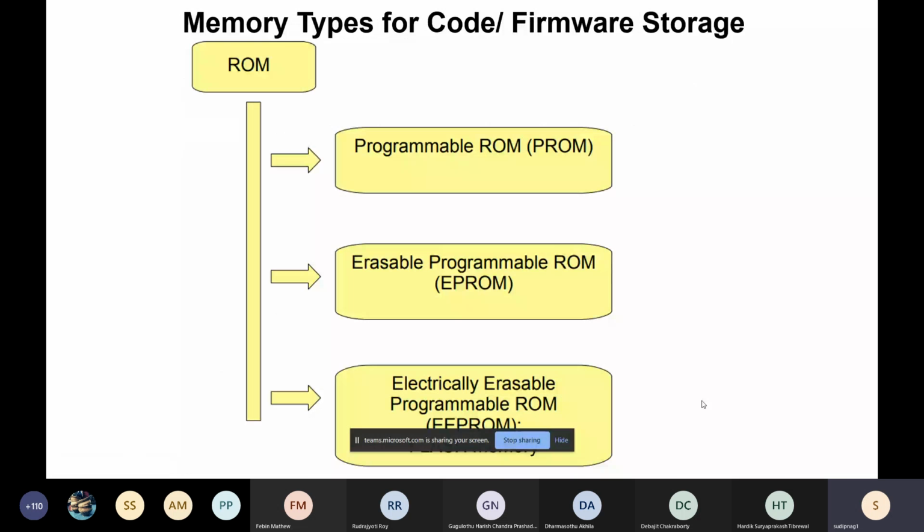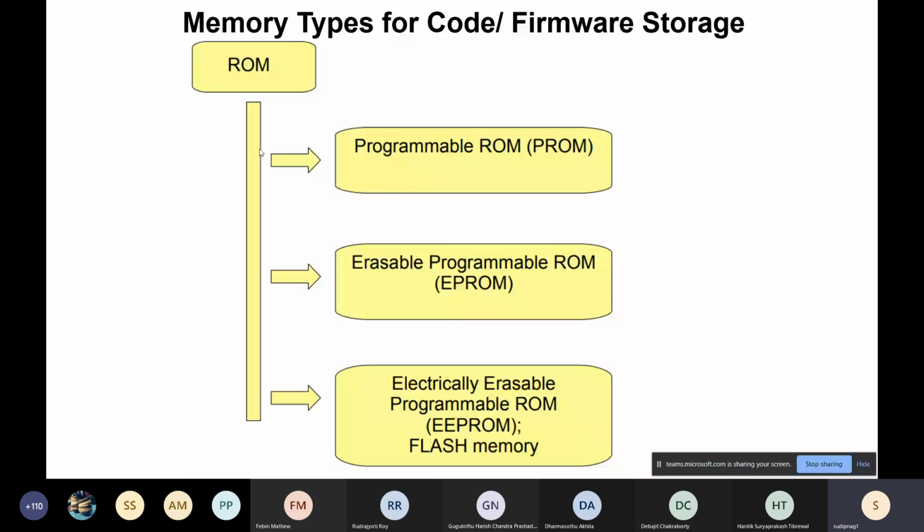So we'll very quickly overview different types of memories that are used in embedded systems. First, the non-volatile memories. These are different types of non-volatile memories, and they are also sometimes called read-only memories, because non-volatile memories may not always be erased, based on the original definition. So non-volatile memory should be programmed only once, but you can do reading millions of times or many times afterwards.